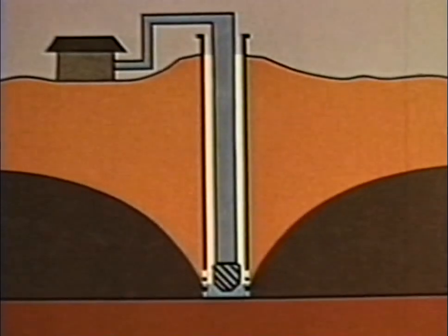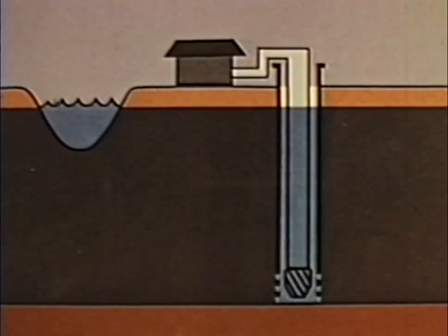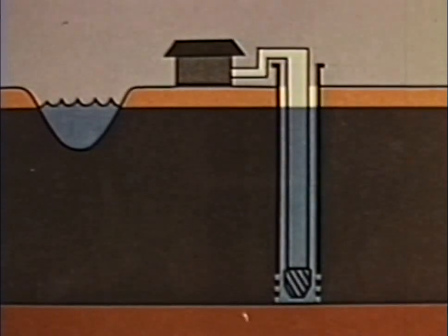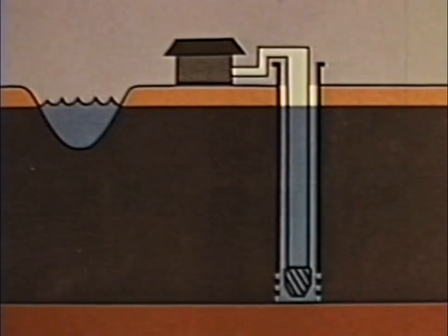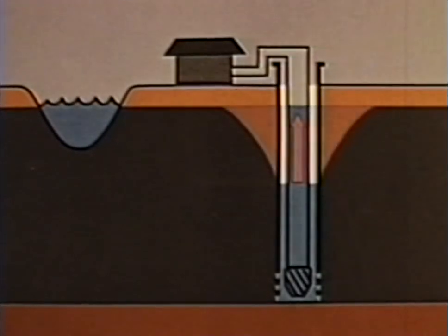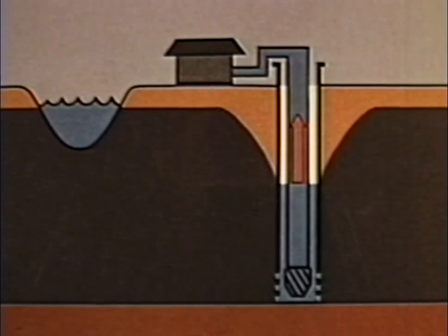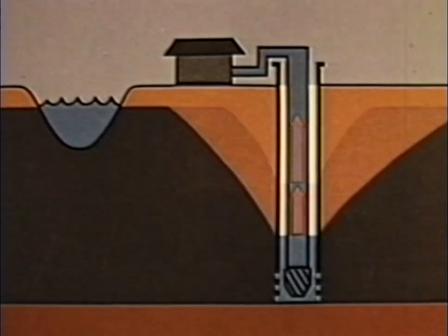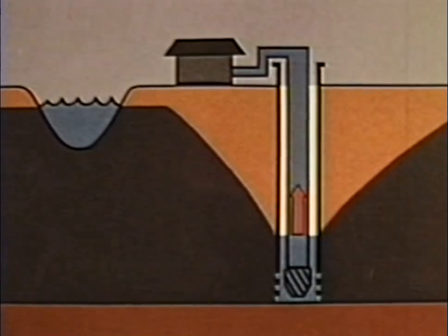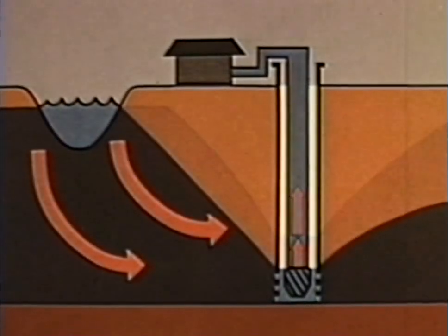Excessive aquifer dewatering can often be avoided if wells are placed near rivers, streams, or lakes. Initial pumping causes rapid decline in the water table. Later, the drawdown cone spreads to the surface water body.